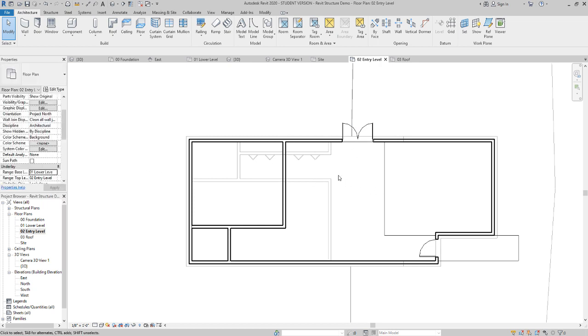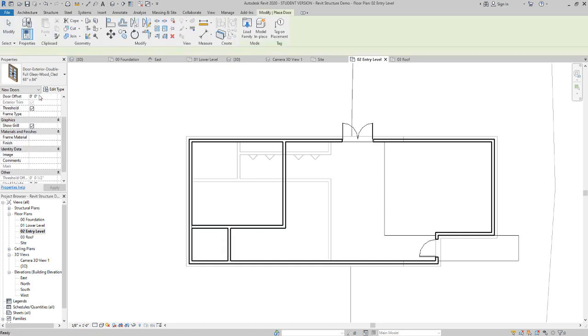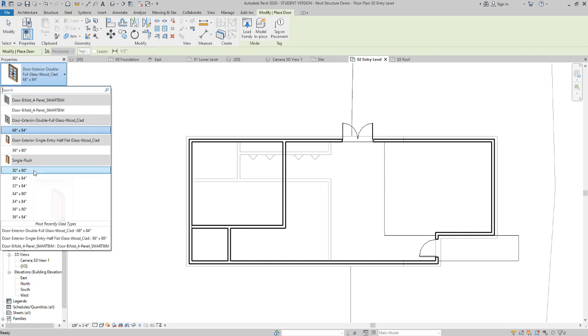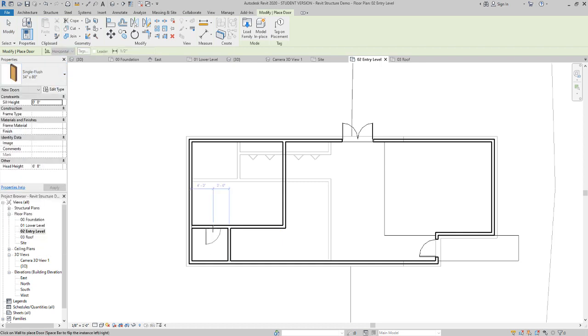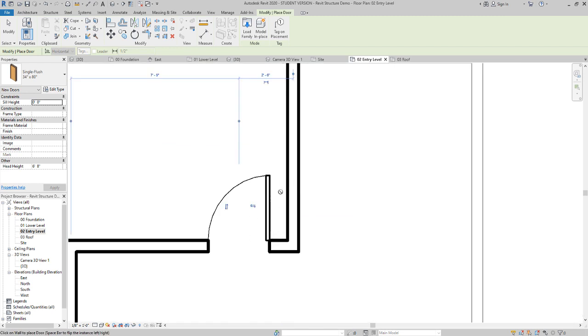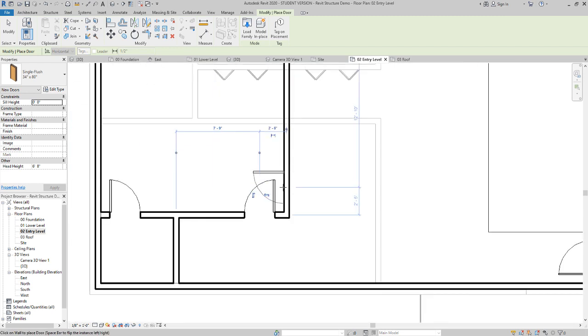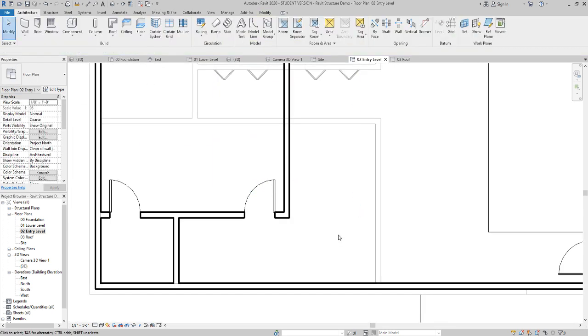And then they want some doors here and here. So we'll just do some regular doors that come in, and I think a 3480 should be fine. It's a residential house. That might be into a closet or a bathroom. And then this one here, I like to hug the wall a little bit more. Make sure you leave room for a door knob, or handle, so it doesn't smash into the door. Escape a couple times.